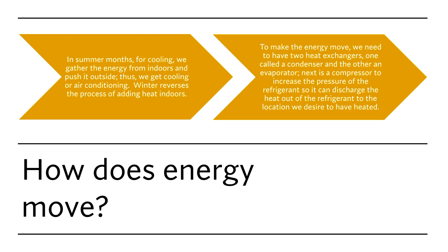A gas, when it is compressed, increases its temperature. So we're going to take it out of the compressor and we're going to move it to a higher temperature. Say it's 110 degrees Fahrenheit, and when the compressor gets done with it, that goes to the condenser unit, and the condenser unit is going to have refrigerant that's in a vapor at 110 degrees.